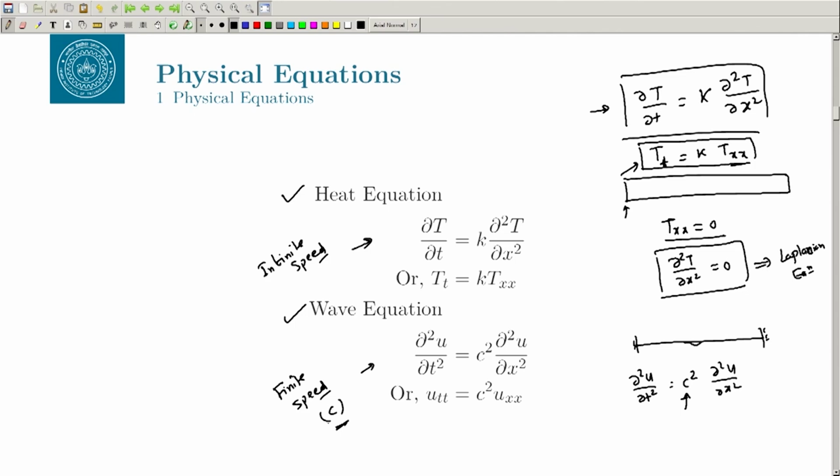On the other hand, if I am speaking to you, the sound is travelling at a constant speed, which is the speed of sound. It can be determined based on the room temperature, and we have talked about this: c equal to square root of gamma R T for the isentropic process, which is fairly valid because we are not adding heat when we are speaking. So, the isentropic process can be assumed, and the sound basically travels.